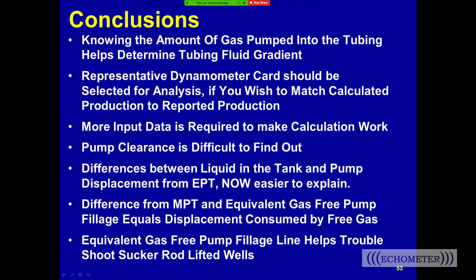Yes, and I would like to clarify that it's asking, is the pump clearance of one side? And I would say, well, the pump clearance is actually the difference in diameter between the ID of the barrel and the OD of the plunger. That's right. You should not consider one side of that diameter, but just the difference in diameter between them. If it was centered, it'd be half the clearance, but we don't calculate that way. Like Gustavo said, it's the ID of the barrel minus the OD of the plunger. Yeah, and that's the total clearance, not the average clearance between the plunger and the barrel.